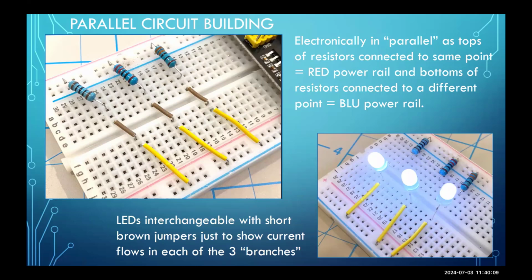Here's another thought. You may have trimmed your resistors too short. Instead of the resistors being trimmed at roughly half an inch, you might have them trimmed at something much less, and therefore one of the ends of the third resistor might not be going entirely into the socket of the breadboard. The same thing is true for these jumper wires. If these jumper wires are bent upwards or something, that could be another possibility. So several possibilities for the third LED not lighting up.